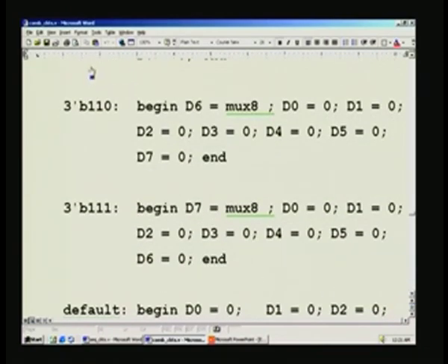Another point I may mention is that you have put everything in a sequential order, say a binary sequence. There is no need for you to do that, and also it may be painful to write so many bits. If you have 64 inputs, you will have to write very many, and the larger the number, the more you have to write. So, a better thing would be to use decimal here. You can just replace this B with D, but even in that case this will mean only the number of bits. So, you have to take the trouble of first computing how many bits it will run into at maximum, then put this. So, this tick is a prerequisite here, and this colon is also a prerequisite here.